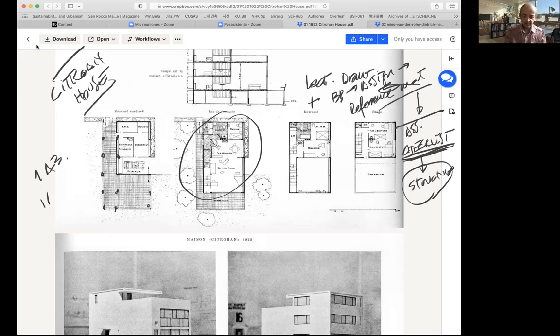So I suggested one A3 for whatever case, and for this building, if you have to make several floor plans and one section, probably 1 to 200 is okay. 1 to 100 is better, but you have to check, because we're working at diagram level, so we don't need to detail a lot. So this is one thing.